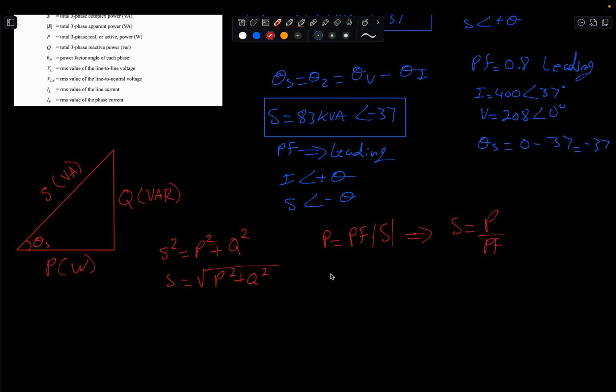And now we know that power factor is cosine theta, and to solve for degrees, it's the inverse cosine of your power factor. And let's say that your theta was given. So in this case, let's say that our theta is 20 degrees. And let's go ahead and give the apparent power. We're just going to put 100 kVA. Based on that, right? So if you want to put this in translation, you're dealing with 100 kVA,